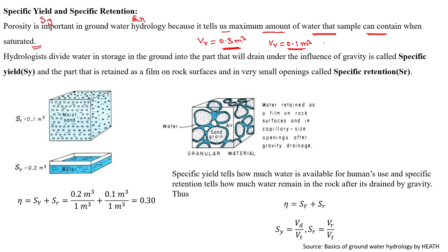In these kinds of situations, we should have knowledge of porosity. Whatever water we supply to the field does not always infiltrate, and does not always make the soil saturated. So we should calculate the total amount of water required to make the soil saturated in irrigation planning. That is the significance of porosity.